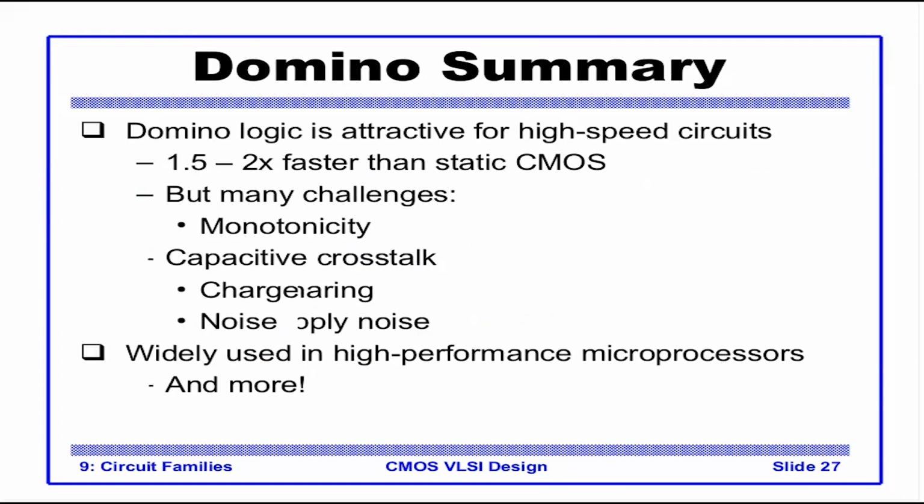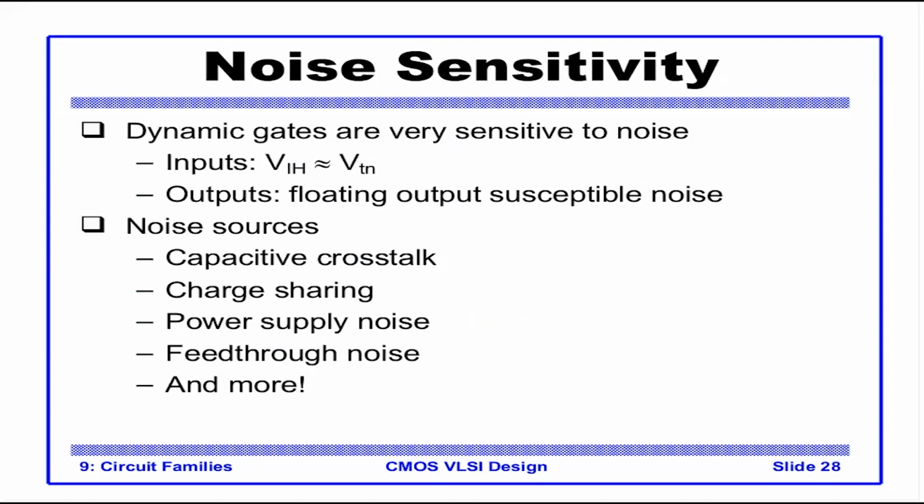Again, outputs. So we saw that outputs are floating in some cases. Let's say if we do not have a feedback PMOS, we don't have a keeper PMOS.